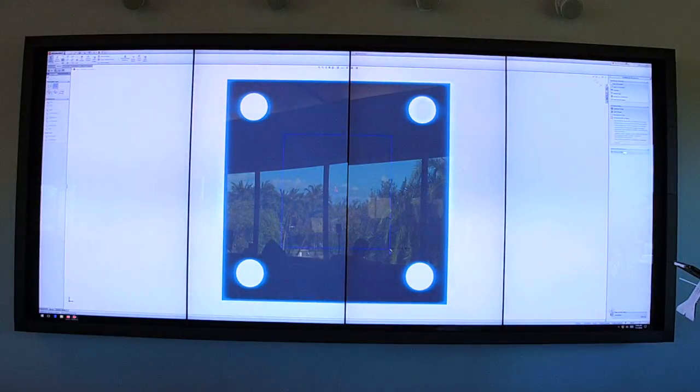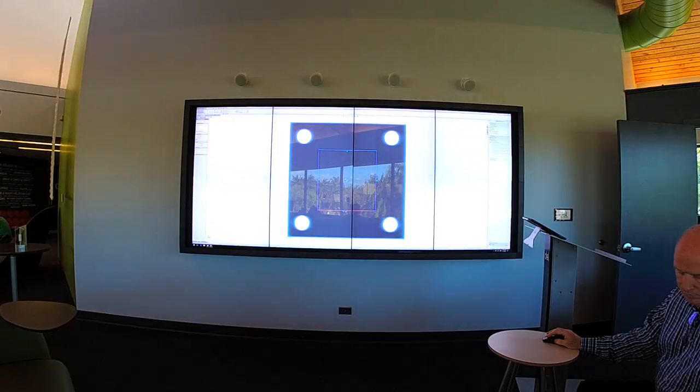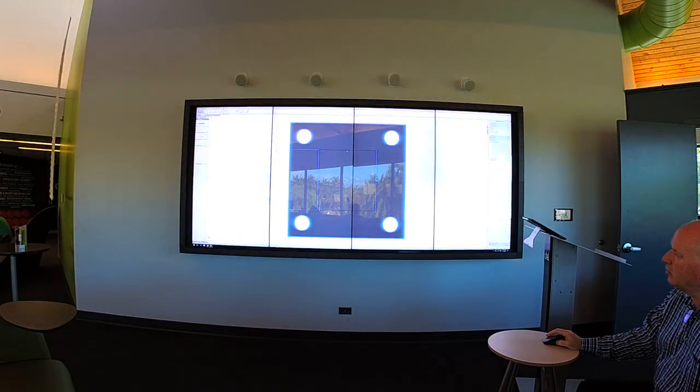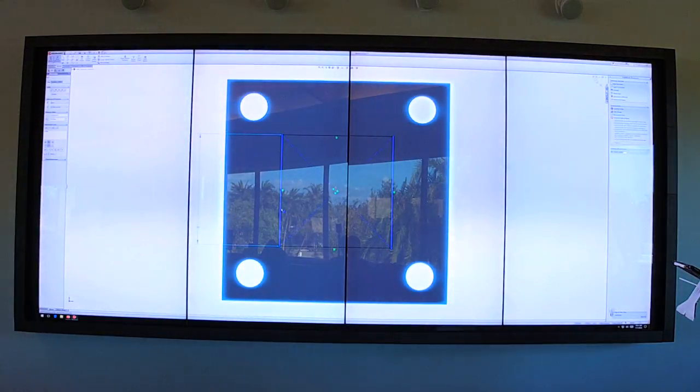I'm going to kind of have that right about here. Okay. Now again, I can size this. I can make the sizes where I want them with the smart dimension. Again, we'll click on top and our bottom. And we're going to make that 20 millimeters. And we're going to do the same with the sides. There we've got that 20 millimeters again. So that's a square 20 millimeters.